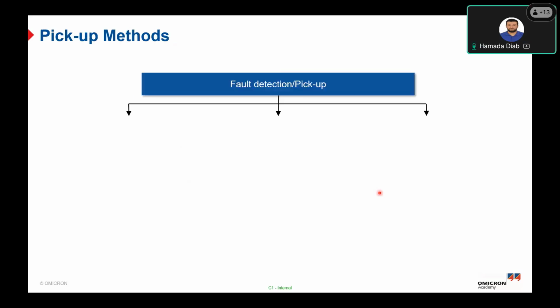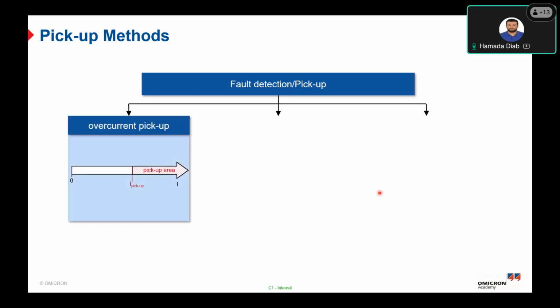We have another pickup method also for detecting the starter logic of the impedance protection. So how to detect the pickup or the start of fault detection? We have different kinds of starter logic. The purpose of the starter logic function is to distinguish between the normal operating state and the fault state. So the starter function must ensure a high sensitivity and also phase selectivity.